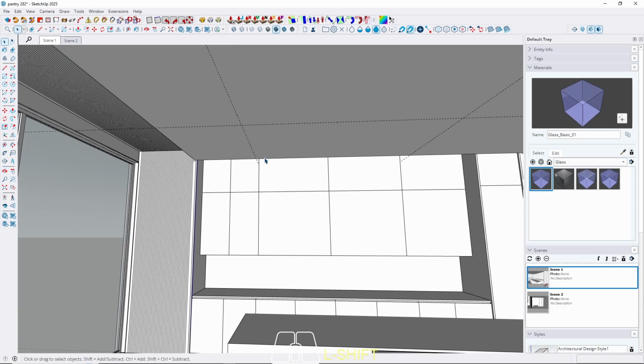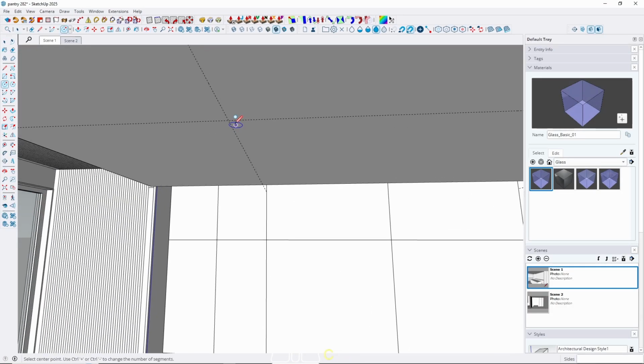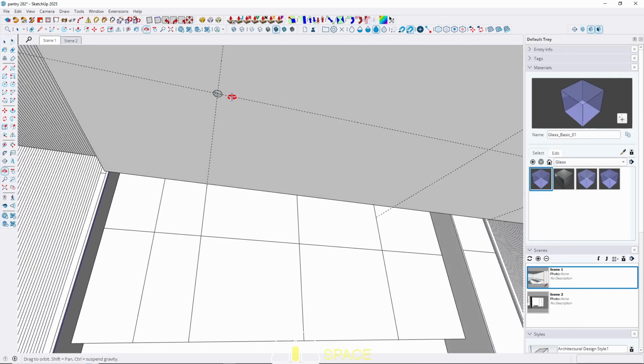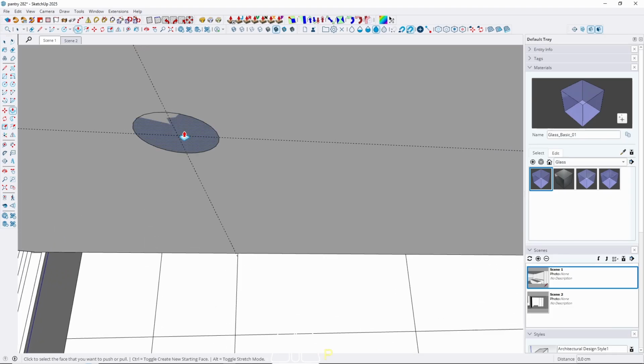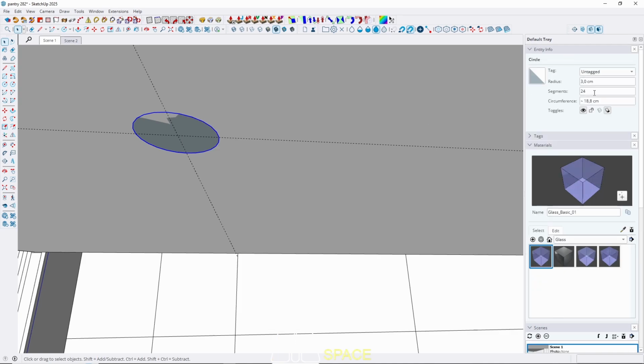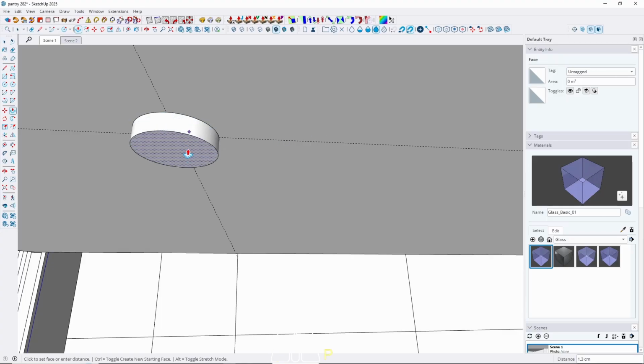Okay, and then let's make the armature. Not too big, it's around 6 diameter or 3 centimeter radius. I want to make it smooth. Let's add a segment into 60, and thickness I want to make it very slim, like 0.5.